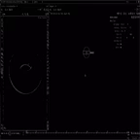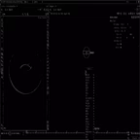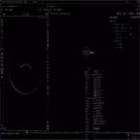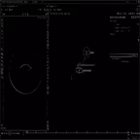But inside of Houdini, there is a different kind of operators, VEX operators. These are operators that you can design on your own using the inbuilt programming language of Houdini called VEX. VEX stands for Vector Expression Language. You can append a point wrangle and connect the geometry, make it visible, and here you can write code.